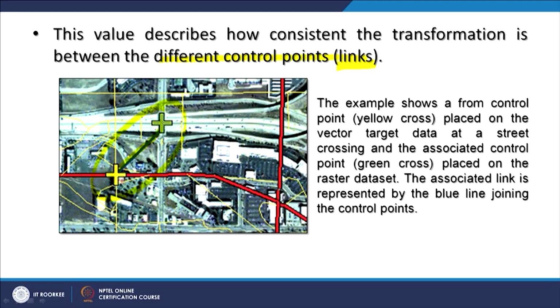If you have, say, 20 points, any point showing a large value automatically has a major or the largest error. Instead of going through the numbers, you can see it graphically and rectify the issue right there. As I have been saying in the case of GIS, error is a very important part, because error propagates in GIS. After each and every operation in GIS, check for errors, and if found, correct them, then go for the next. Do not leave errors for others to correct.